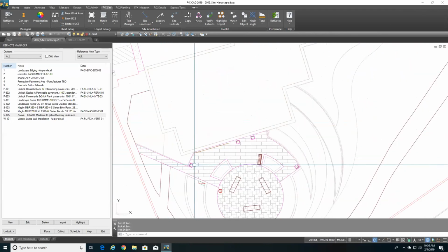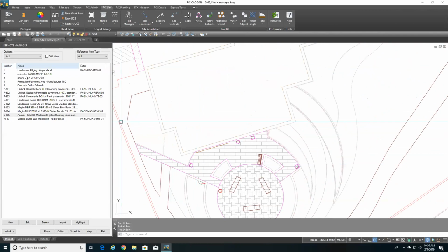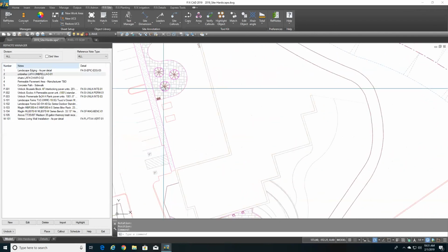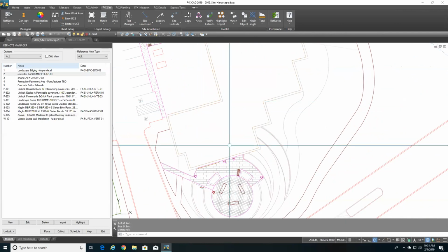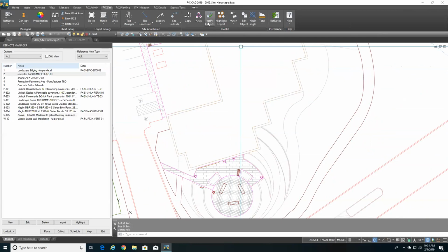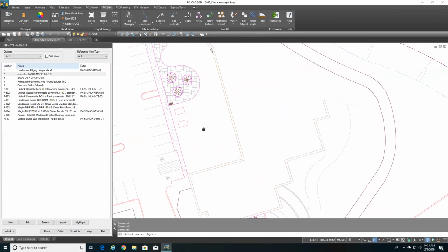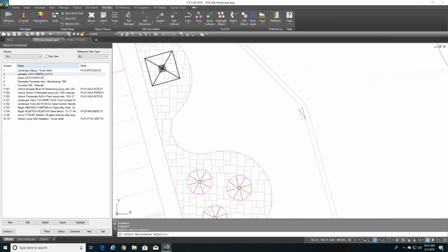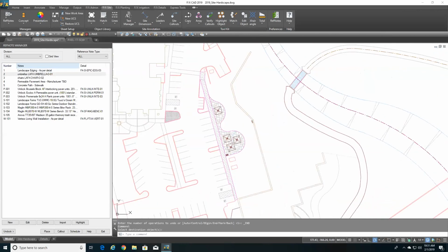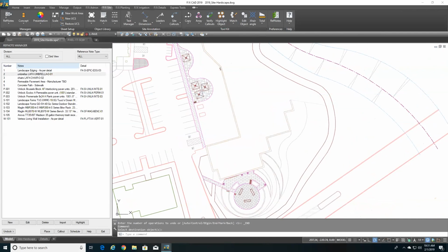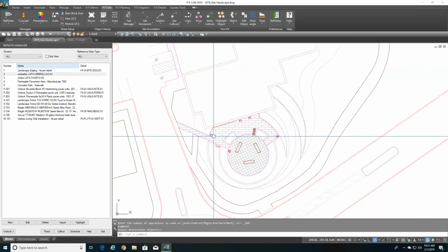got some of these generic objects like I do in my plan, the umbrellas, which are located right here, what you can do is, if you have then placed some smart objects in your plan like I just did, you can use the, where is it? The match properties tool. Okay, so this basically allows you to pick a source object and then turn that into that smart object, which is just really cool to be able to do so quickly. You know, you don't need to delete and then replace anything.